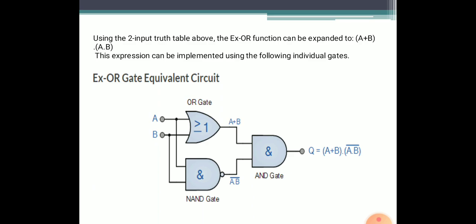Pseudo random number generators, specifically called linear feedback shift registers, are described in terms of the exclusive OR operation. Thus, a suitable setup of exclusive OR can model a linear feedback shift register to generate random numbers. Exclusive OR gates form a 0 output when both inputs are matched. We learned this from this class.